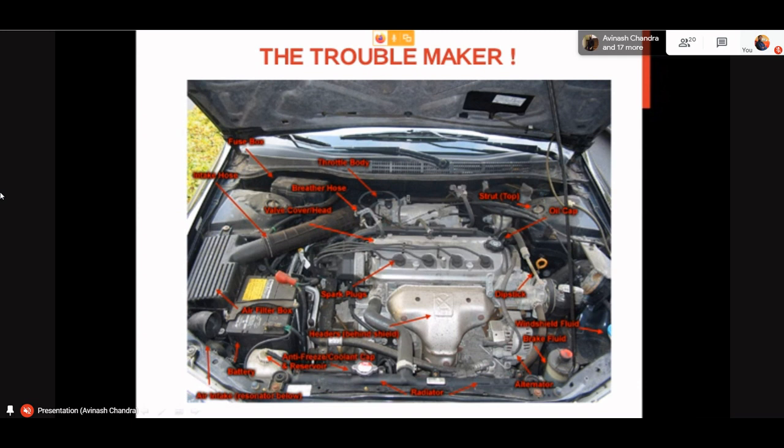The engine typically generates 127 to 130 degrees Celsius of heat, but the exhaust generates a lot of heat, because the exhaust is taking away the combustion gases. That can go up to 600 to 700 degrees centigrade. So if I say engine bay, engine compartment or the underhood compartment, the thermal analysis is kind of important, but if we compare with the exhaust, it's not that important.